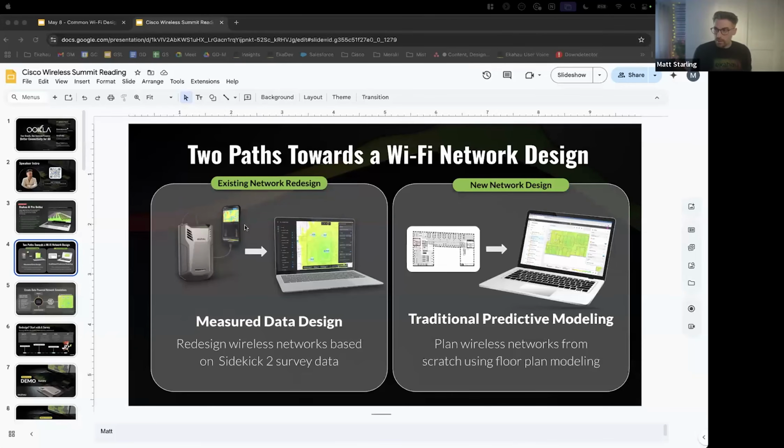And yeah, found it. Let me go ahead and share my screen again. So the thing about Ekahau AI Pro Online is we give you two options for how you can predict and model your space. The one on the right-hand side is probably very familiar to all of you, where you would upload a floor plan, define a scale, add the attenuation values for all of your materials like walls, cubicles and warehouse racks, and then place your simulated access points on the floor plan, and then we predict and show you the heat map and coverage.